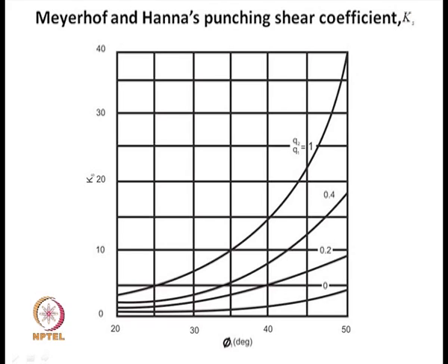So, that means this Ks value will be required to calculate the ultimate load carrying capacity of this layered soil. The Ks term is there, as you have seen in the final expression. So, there we will use the Ks. That is for when phi 1, the top layer, is stronger sand, because we are getting the Ks for the phi 1.